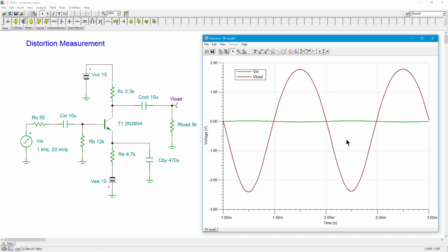All right. So the first thing is I want to figure out what the THD is, the total harmonic distortion. We represent that as a percentage, right? You'll say the THD is, let's say, 1%. What does that mean? If this waveform were 1%, it's 99% pure sine wave that we started with, and then 1% is these extra harmonics, these extra frequencies, all summed together. The lump of them works out to 1% of the total.